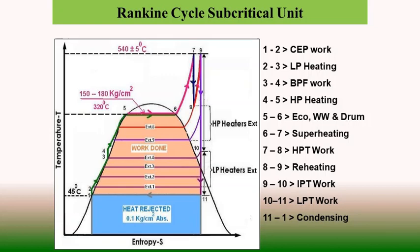When this final superheated steam is expanded in the HP turbine, the majority of the steam is going for resuperheating or reheating, but from the exhaust of the HP turbine the first extraction is taken for the HP heater. After reheating, when the reheated steam is expanded in the intermediate pressure turbine, another extraction is taken during expansion, and that goes to the second HP heater.